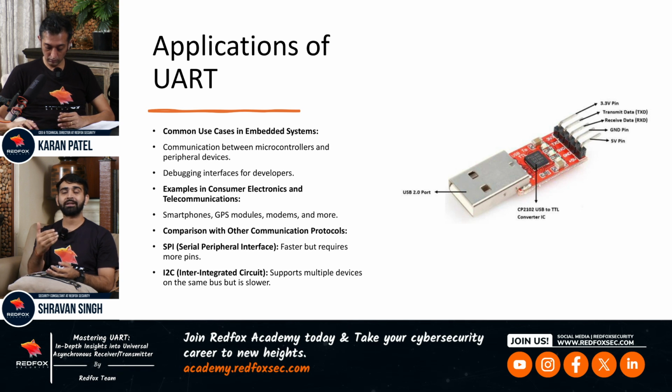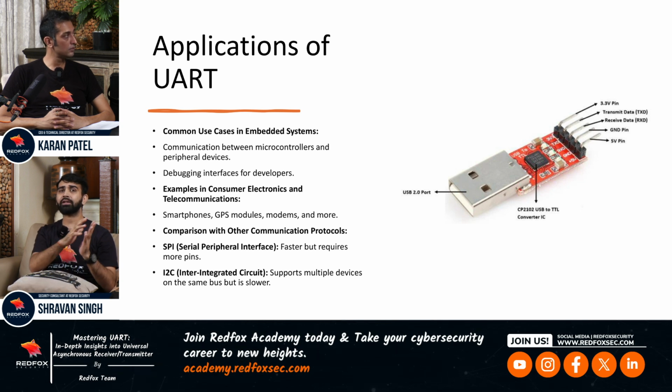If you take the example of a Chinese company, they are making products for the industry, introduced in the industry first, and after that the product is distributed to home consumers. In those devices, if you check, the UART section is easily accessible, and from the device you can check the whole boot process, the kernel image, and all the data being transmitted.